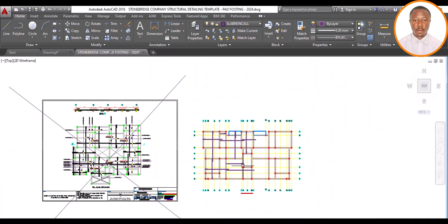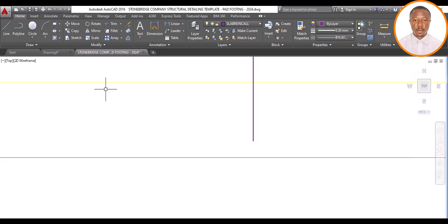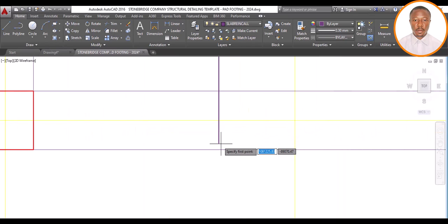No, okay, remain small, because this slab we have not finished. So we are going to do what? Carry our line, pick our lines, and come to this place. Come here, click, and also take my reinforcement to this place. So I need to take my reinforcement spacing, which is 25, inside. Okay, it's okay. Because of my formwork, the space between my formwork and my reinforcement, which I've explained before. So then 100, move it by 100, and take it in by what?